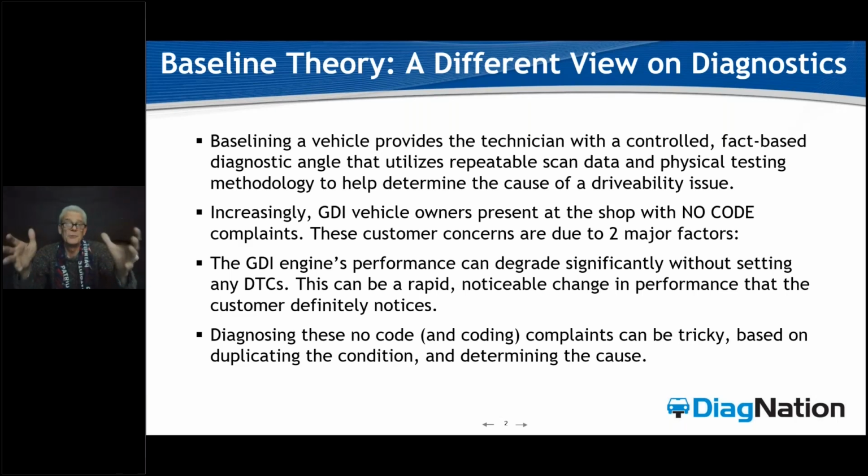For example, if it's a 3.5 liter V6, there's a given volumetric efficiency in that engine that's loaded into the fuel maps. Now consider as we build up carbonaceous deposits all over that engine, and we're going to cover the main 4 deposits and where we're seeing them in the vehicles today.